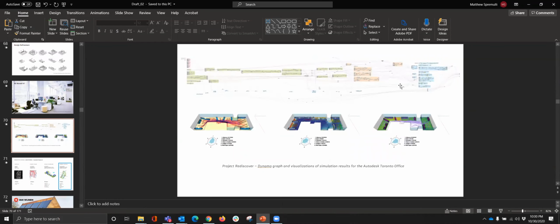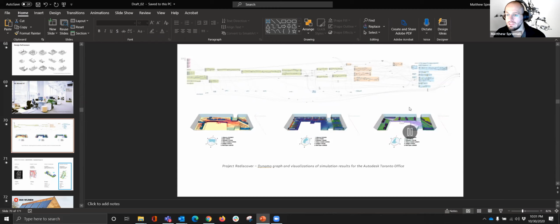For each of the goals, if it's a custom equation, you would make that custom equation inside of an equation node inside of Dynamo, or something like a Python node if you wanted, or you could build it more manually with lots of different nodes together. But you can change it, of course, at any time. It's just how you want to measure each of your designs.